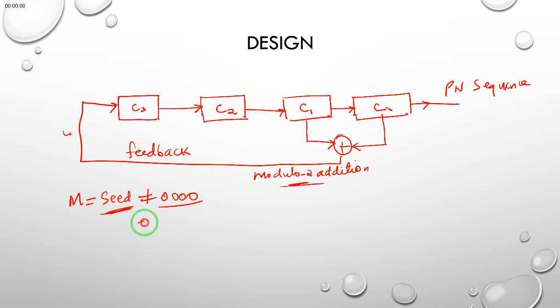So for us, we can start with 1, 0, 0, 0 as our starting code. Therefore, this is 1, this is 0, this is 0, this is 0, like when we are talking about flip-flops, they are initialized to this state. So we will now see what happens. For instance, 0 XOR 0 is taken as the output. We know 0 XOR 0 equals 0, so our first 0 will come there.